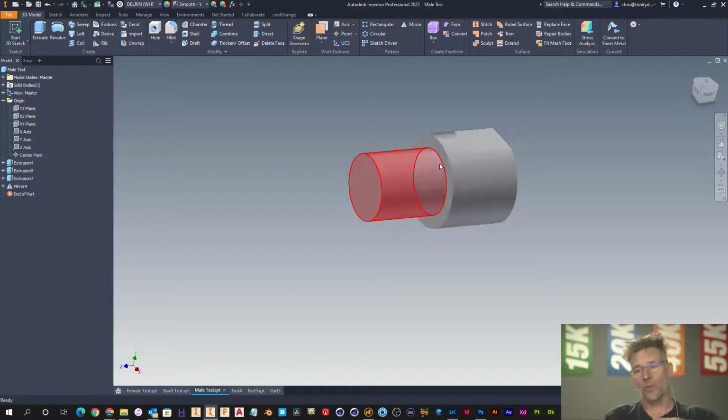And there's 2 ways to look at doing the relief cut. One is that you're just doing a relief cut just so you can finish that thread out and have it nice, and your stuff's not going to crack or break or things like that, but it just looks cleaner. Or 2 is this part might end up having an O-ring that slides over the thread to seal this part if it's a high pressure part. So we'll just take a look at what we got here.